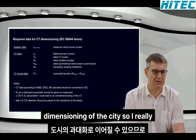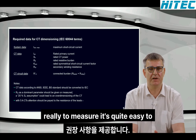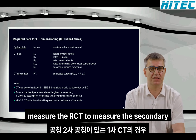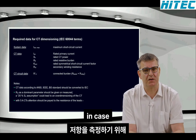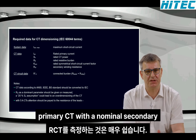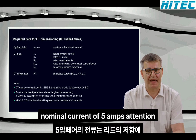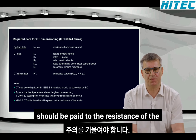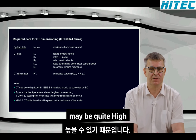So I really recommend to measure the RCT. It's quite easy to measure the RCT, the secondary winding resistance of the primary CT. In case you use a primary CT with a secondary nominal current of 5 amps, attention should be paid to the resistance of the leads, because then the resistance may be quite high.